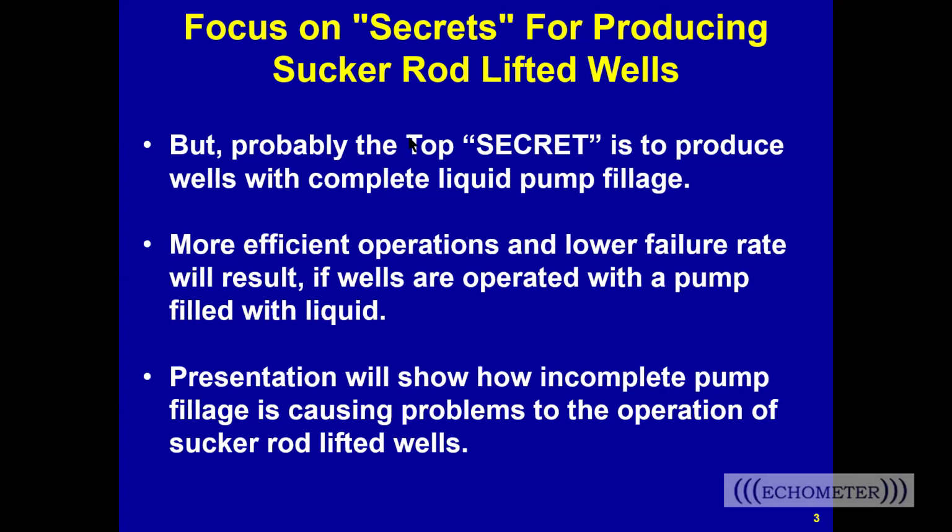One of our practices when I worked for a production company, Emerald AS, in the past, was at all costs to maintain a pump filled with liquid. We believed that would reduce our failure rate, and we saw that we had a low operating cost and a low failure rate. So I'm a large proponent of maintaining full pump fillage when you operate a sucker rod lift well, but you also still have to follow the other recommended practices, because you can't do one right and another one wrong, or you'll still have an operating problem. All right, Carrie, I think you're next.